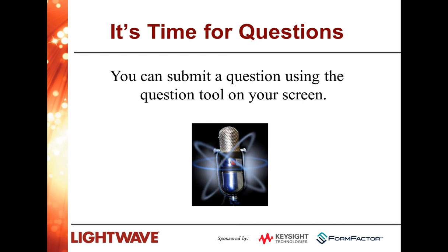That will work, but there are some caveats that need to be paid attention to, because with semiconductor optical amplifiers, the performance depends a lot on the input power. So you need to be very careful that you understand the input power that's being delivered to the amplifier. In addition, once you've got the parameters set straight and the amplifier has gain, of course, you need to pay attention to whether amplified spontaneous emission is corrupting the result. But in general, it should be possible to scan an amplifier.